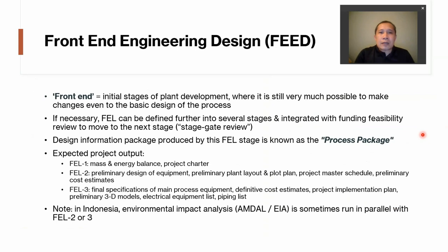Now let's do a quick review about each of those design stages. Okay, so the first one is FEED, or front-end engineering design. Front-end refers to the initial stages of plant development, where it is very much possible to make changes even to the basic design of the project. Okay, changing the PFD is still very easy at this point. And if necessary, FEL or FEED can be defined further into several stages and integrated with funding feasibility review to move to the next stage.